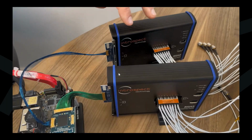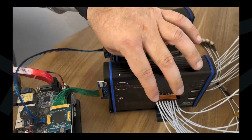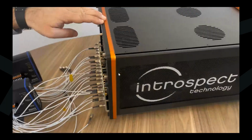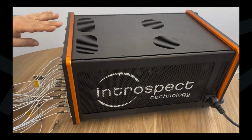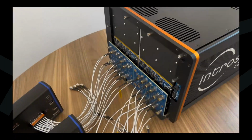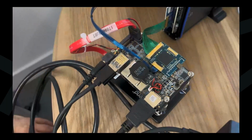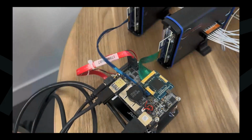The output of the RSH is just like any active probe solution, so it can go to an oscilloscope, or it can go to the Introspect Technology M7030 DDR LPDDR protocol analyzer. This is the latest product from Introspect Technology, and it addresses the highest speed applications for memories with a high sampling rate, with advanced features like supporting clock stops and clock frequency changes, and unterminated CA operation, as well as nested triggers and nested commands for different applications.